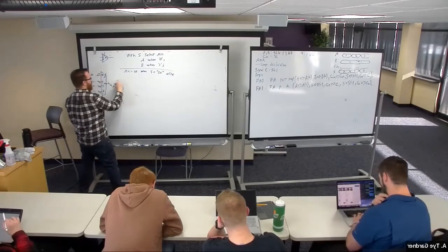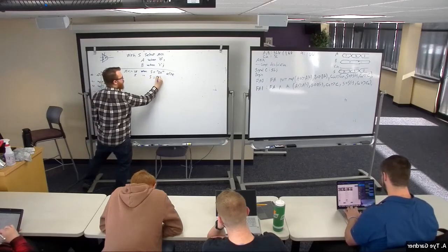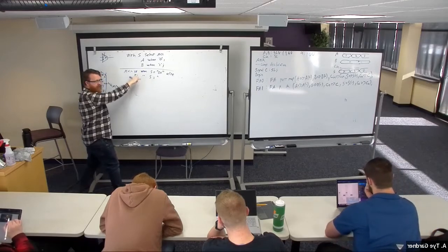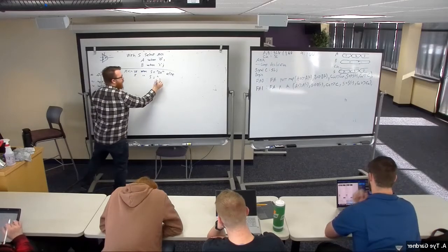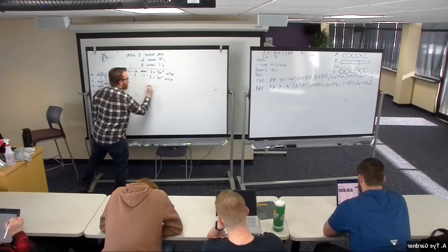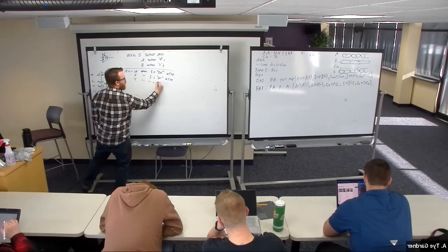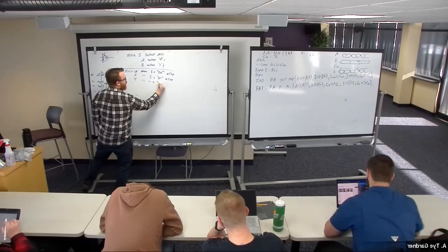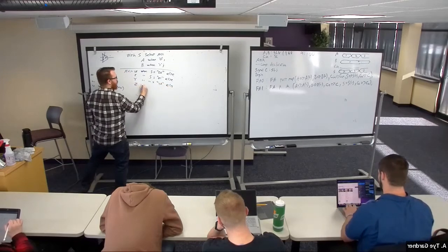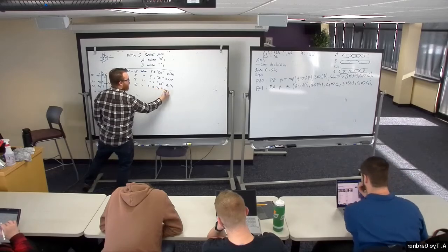Else, W, X, when S equals, so quotes like this, if you're not familiar, just mean copy the line directly above it. 0, 1. Else, Y, when S equals 1, 0. Else, Z, when S equals 1, 1.